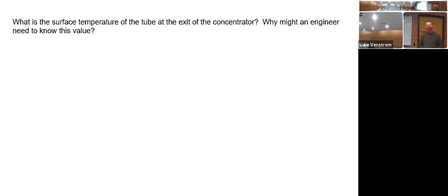It's gone, it melts. But even if it's not melting, imagine for material science, you learn something about creep, right? So things that are warm tend to creep faster. So this thing is 17 meters long, and it's basically a big tube, more or less pinned at two ends. So think about the creep that's going to happen over time. The tube that started as a straight line over time is going to tend to bow and bow and bow. So being able to know the temperature of the absorber is really important for predicting things like how much creep we anticipate,